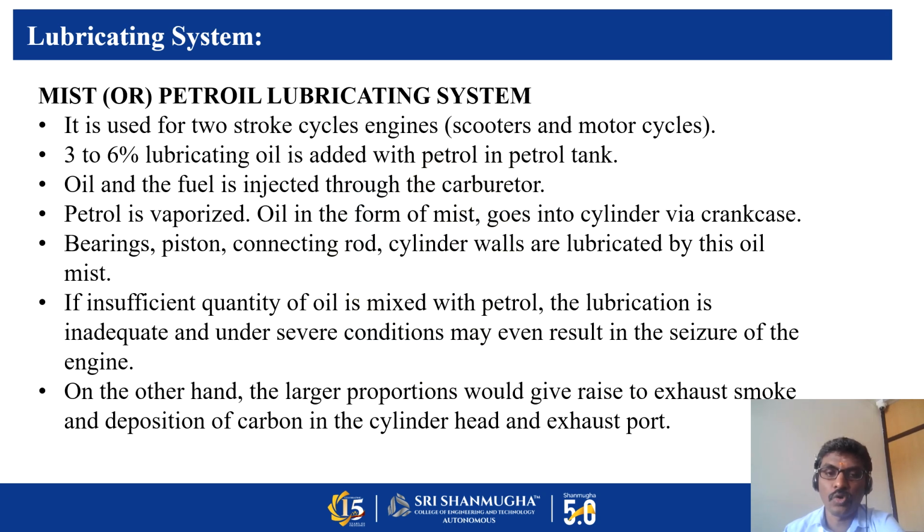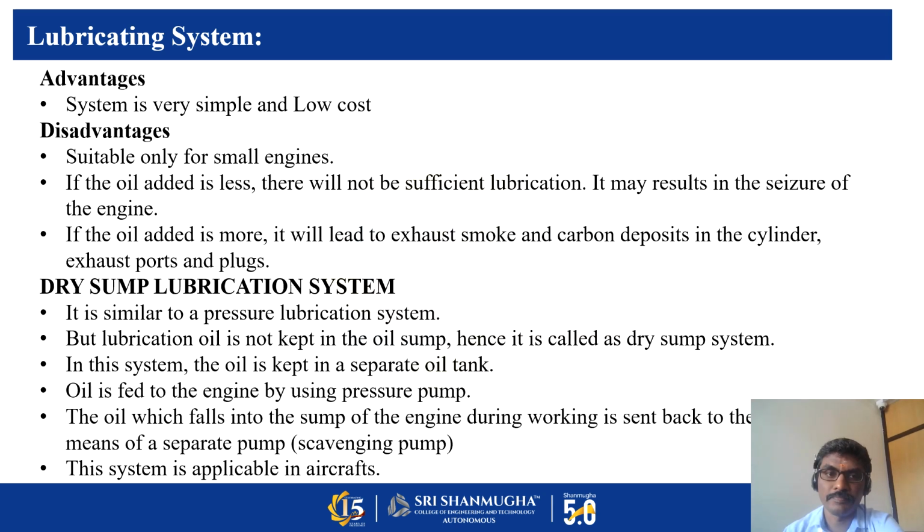If insufficient quantity of oil is mixed with petrol, the lubrication is inadequate and under severe condition may even result in the seizure of the engine. So you have to maintain the proper level of oil in the engine. On the other hand, a large portion would give rise to exhaust smoke and deposition of carbon in the cylinder head and exhaust port. So advantages, system is very simple and low cost.